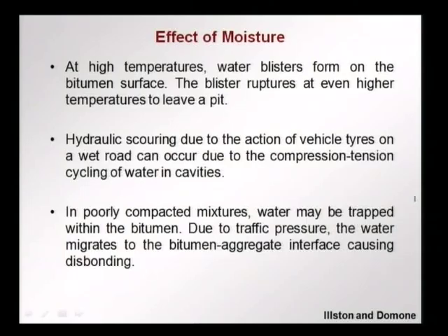This pit develops further, water is now pushed into the pit by the tires and hydraulic scouring occurs, that is, water is pushed into the pit as the tire is approaching the pit, and as it leaves the pit the water is pulled out. So, this repeated action of water being pushed in and out of the pit makes this pit larger, makes the damage worse, and it facilitates the stripping of the aggregates.